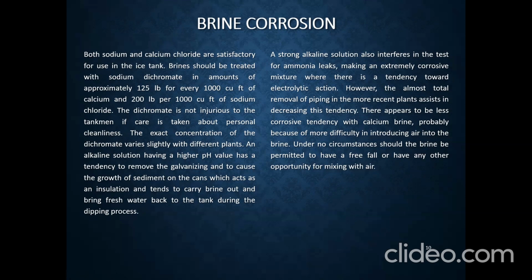There appears to be less corrosive tendency with calcium brine, probably because of more difficulty in introducing air into the brine. So under no circumstances should the brine be permitted to have a free fall or have any other opportunity for mixing with air.